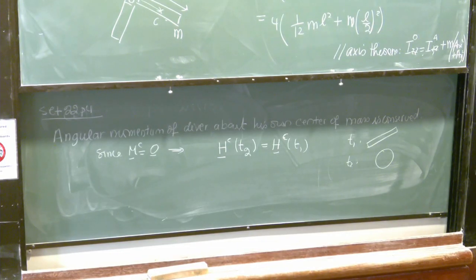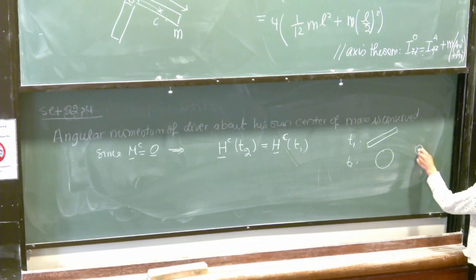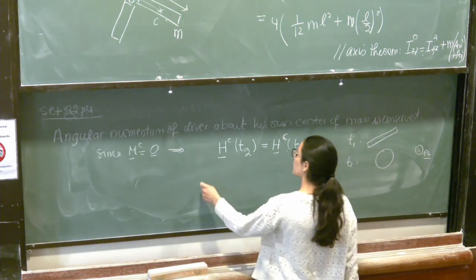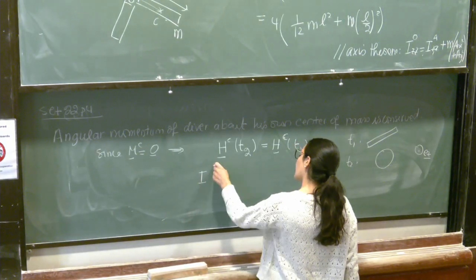And what we're considering here is a planar rigid body motion, where what is the axis of rotation in this problem? Where does it point? Into the page or out of the page, so perpendicular to the page, right? Doesn't matter if it's negative. So the angular velocity is along e_z, making a few symmetry assumptions. Then the angular momentum is going to be I_C.